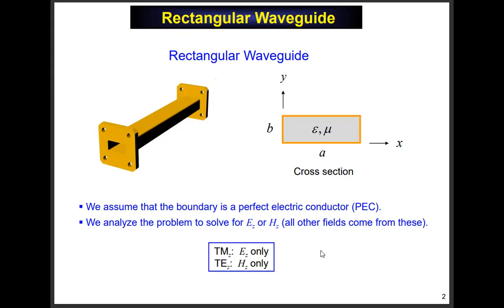Now, you can prove, although I'm not doing it here, that you'll never have a TEM wave propagating in a hollow pipe of metal like a rectangular waveguide. If you could hypothetically have a TEM wave in a hollow pipe of metal, then like any other TEM wave, KZ would be equal to K, right? So if it's a hollow pipe of metal, that would be wonderful. If I had a mode going down it where KZ is equal to K0, just like a coax or a plane wave, I could go down to zero frequency, any frequency I want. That'd be wonderful.